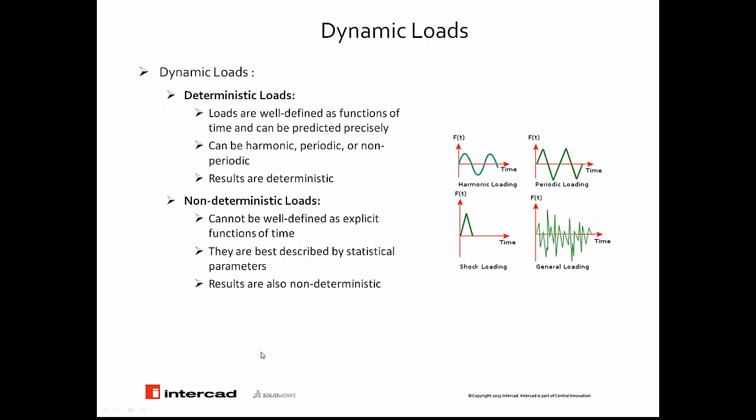Let's have a closer look at the dynamic loads. We simply categorize them into deterministic loads, where the loads are well defined as a function of time, and we can predict their behavior or fluctuations precisely. They can be harmonic, periodic, or non-periodic. With such a loading and performing a dynamic analysis, we get a deterministic result as well, meaning an absolute and precise result. In some cases, we can't explicitly define our loading as a function of time.